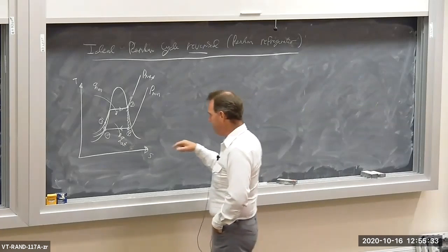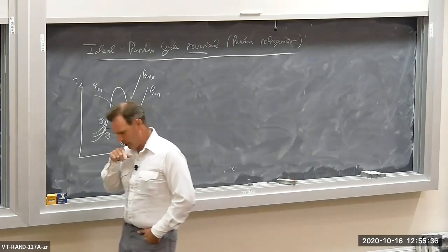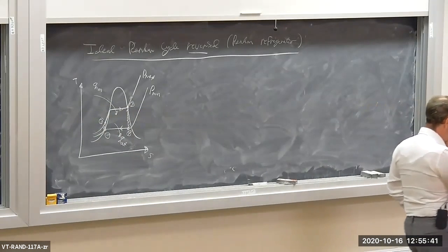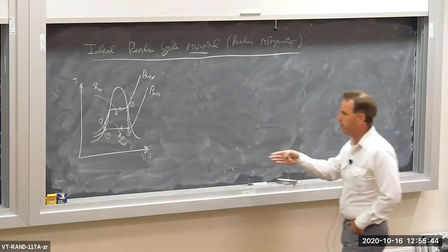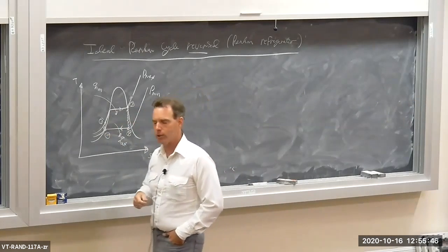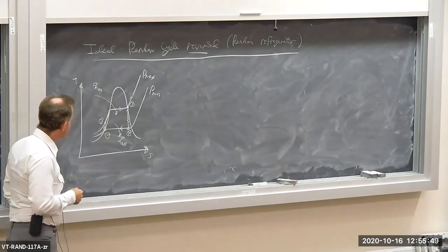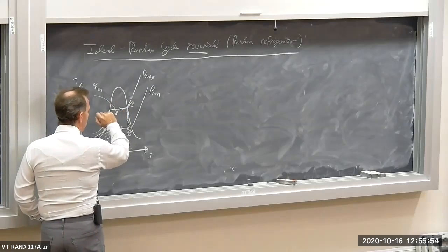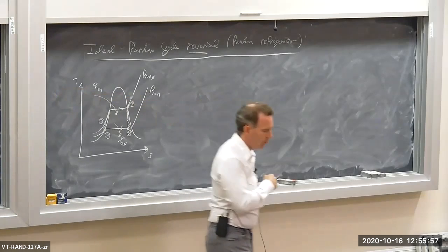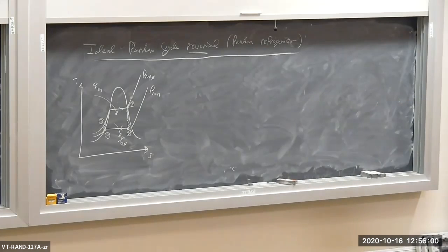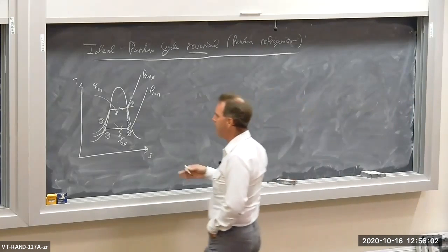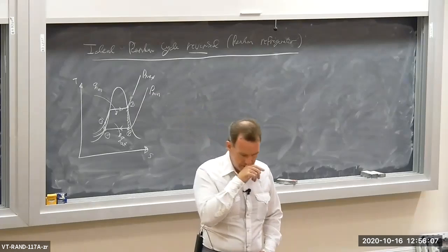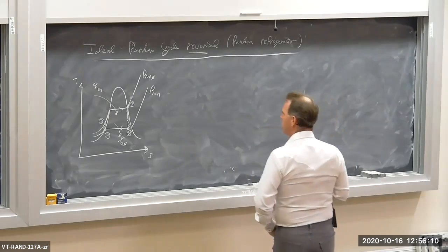In the examples that we've done, superheated vapor for state 3. So we have superheat, and then we have non-ideal pumps and compressors. So these wouldn't be isentropic compression and expansion processes. So in the example that we did, okay? And of course, in real life, it's possible to have pressure changes as we go through the boiler or through the condenser, but we didn't deal with that. Now let's reverse this thing. Internally, this thing is reversible. The isentropic efficiencies are 100% for the pump and turbine. So we could reverse this thing.